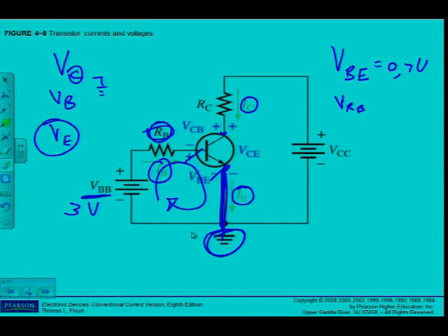Alright, so VB and VBE will be the same, because VB is measured with reference to ground, from base to ground. We've seen that is approximately 0.7 volts. But if I measure VBE, remember we read from left to right, so the red lead goes onto the base, the black lead goes onto the emitter. What will the value be?